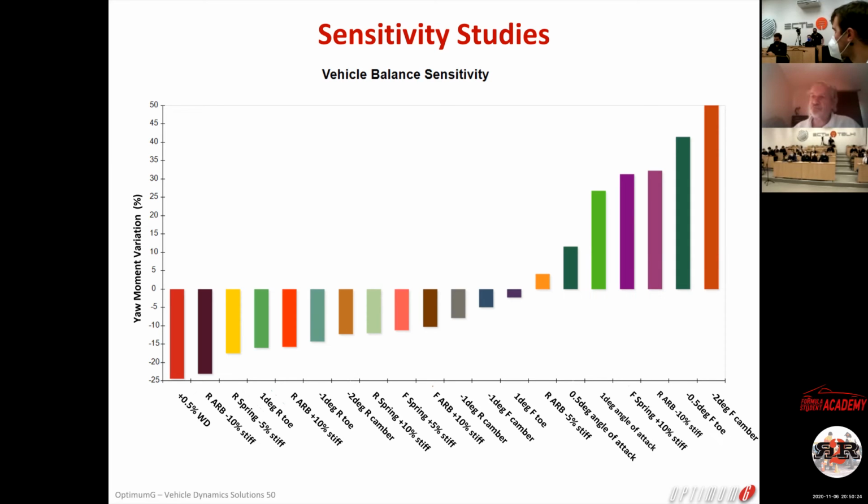When you have design and setup parameters, okay, when you design a car, I'm speaking about the GT, for example, do you put the engine on the front, the engine on the rear, Porsche, or the engine in the center? BMW engine on the front, Ferrari engine in the middle, Porsche engine on the rear. So these are things you cannot change when you go on the racetrack. It's too late. Your weight distribution, maybe you can play a little bit with the ballast, but okay. Pickup point, most of the time, it's too late to change it. But setup means you can change the spring, the anti-roll bar, the ride height, the caster, the camber, the tire pressure, the toe.